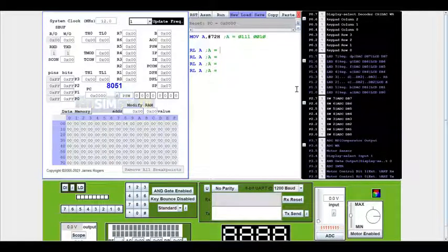So what happens? It will be 1 1 1 0 0 1 0, and the LSB will be the MSB. MSB will move to the LSB. Again rotate to the left, so that will be 1 1 0 0 1 0 0, and MSB will move to the LSB. So still it is not 27, so we will see how many times it should be rotated.